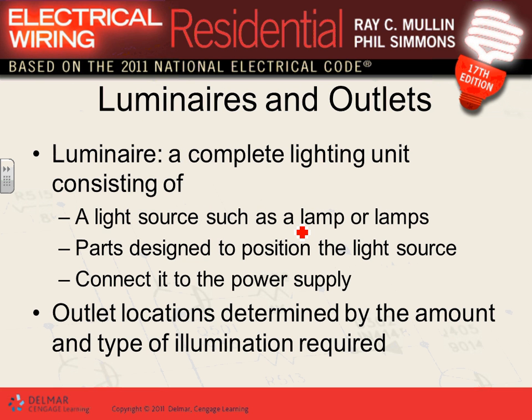Okay, luminaires. You guys will learn about luminaires more than you even need to know. Luminaire is right above your head. It's a complete lighting unit. The diffuser, can you guys see that cover? That's called a diffuser. Right underneath the diffuser, you have the lamps. These are the source of the light. What drives the lamps is a ballast. We'll talk about the ballast that drives the lamps. The ballast, the diffuser and the lamps are all housed in a housing, right? You can't just put the lamps right up in the air.